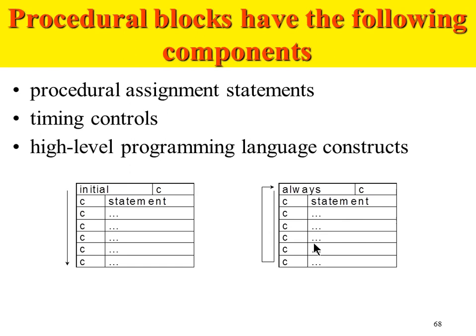Let's say there is a chunk of logic, and there is chunk number one and chunk number two. Chunk number one needs to go into always block number one. Chunk number two needs to go into always block number two. That's how logic can work parallel with respect to each other, because both always blocks will get executed in parallel. So that is how parallel logic can be built using the Verilog language, which is used for hardware description.